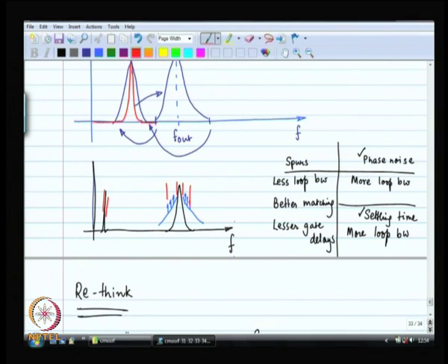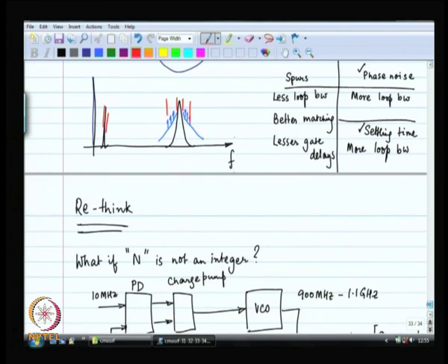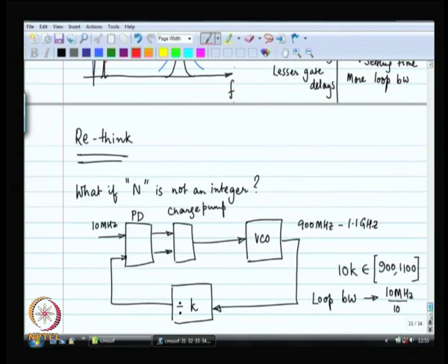Okay. We looked at the importance of phase noise earlier on, when we were working on mixers, right. So, the VCO phase noise is going to be irrelevant within that loop bandwidth. Outside the loop bandwidth, of course, the VCO should have good phase noise performance, right. So, is this a better approach? What do you think?